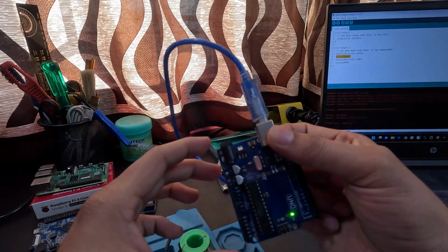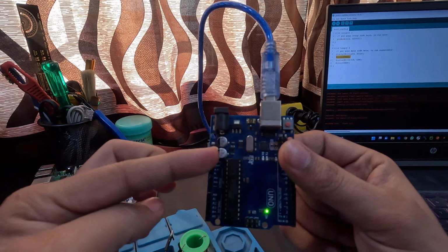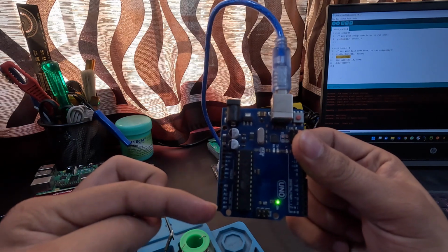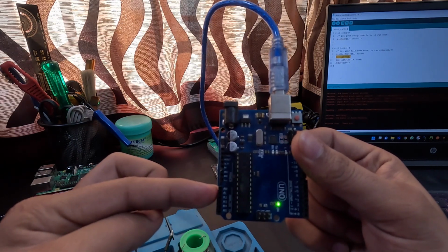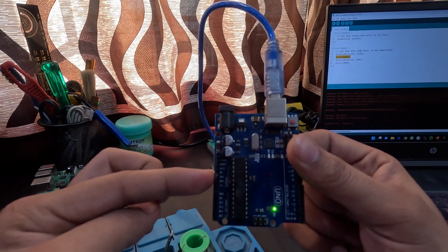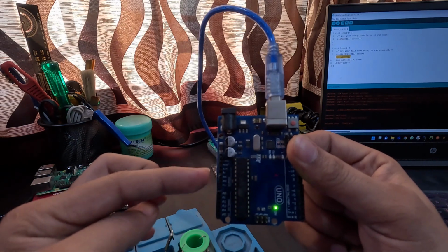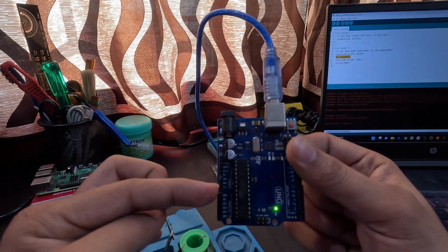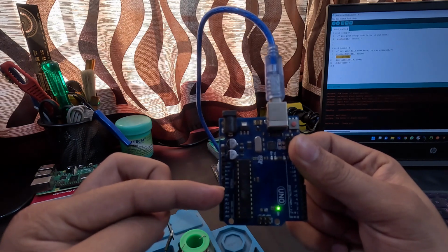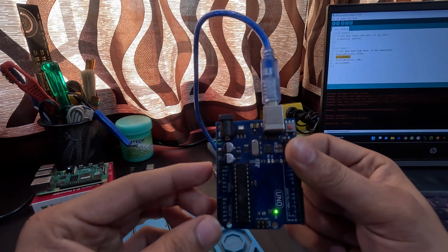As you can see in Arduino Uno, we have different pins, which if we start from the lower side, we have A5 to A0, then Vin, then two grounds, 5 volt, 3.3, reset, and IOREF. In Vin, if you want to give an external supply, we will be giving it to the Vin pin. It supports up to 12 volt.